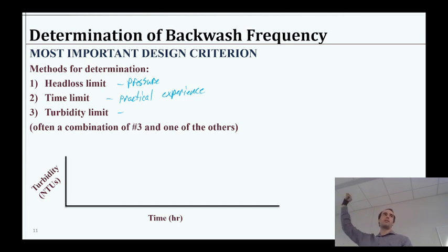If you have a sudden spike, there's a big problem, right? Maybe fissures happened or something. But generally you could see like a small increase over time. Some of the particles start making their way through. So this would be probably used in conjunction. You'd normally have this as kind of a safety factor, right? So you should have ongoing turbidity monitoring. So we'll say sort of a safety measure in a sense.